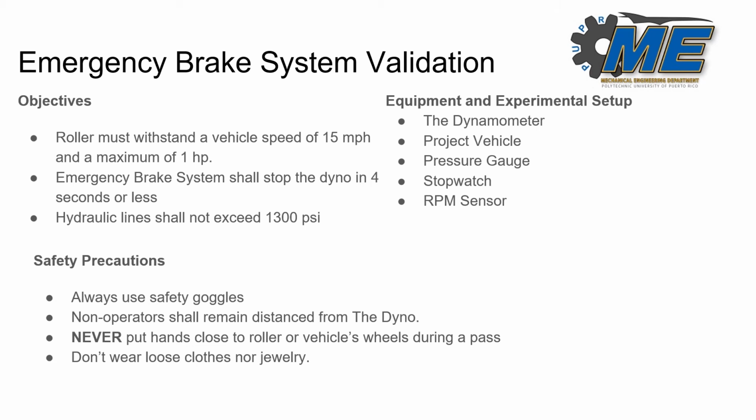The safety precautions that are needed for this experiment are: always use safety goggles, non-operators shall remain distant from the dyno, never put hands close to the roller or vehicle's wheels during the pass, and don't wear loose clothes